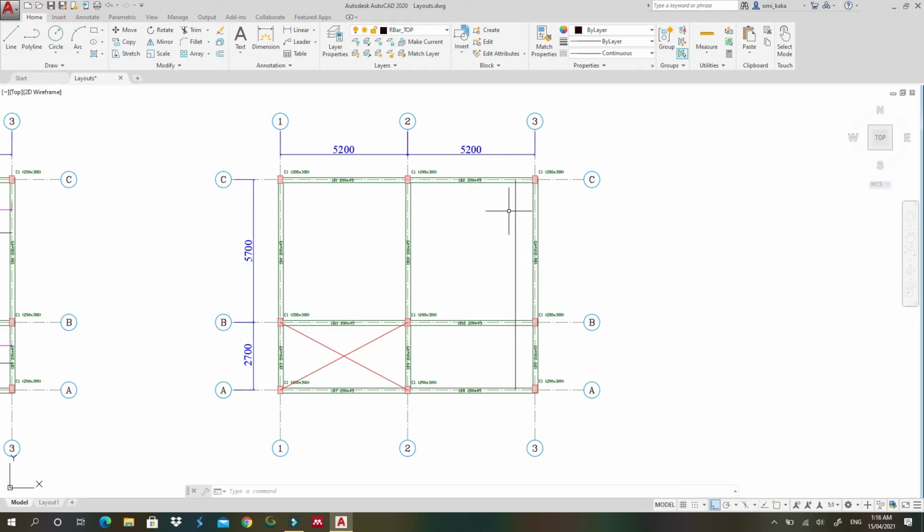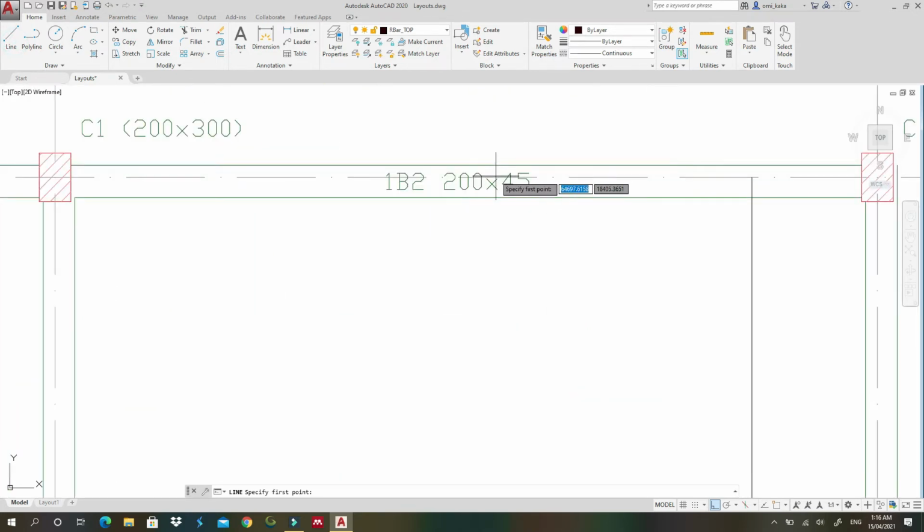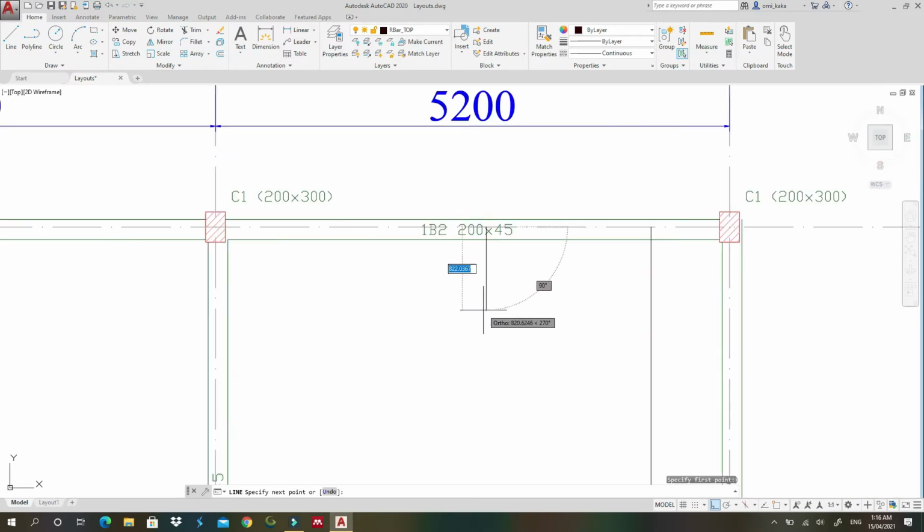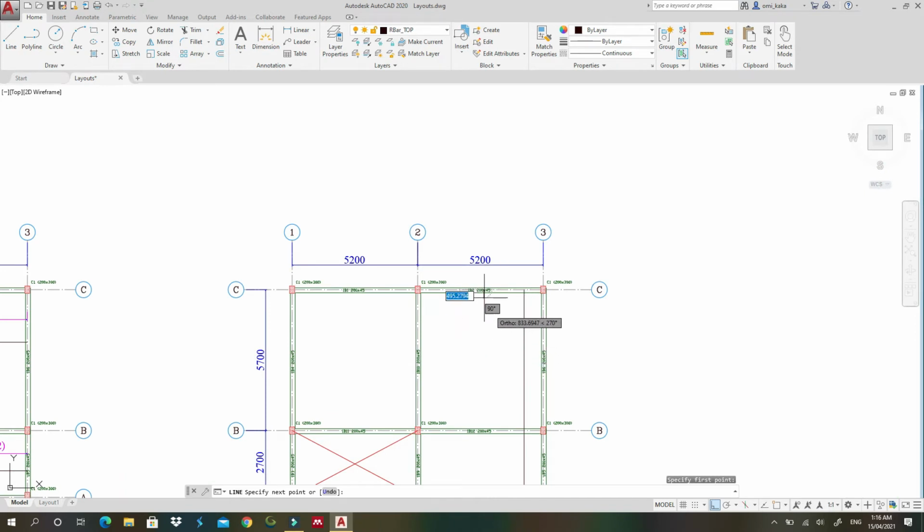So he'll arrange the first one, the second one, the third one, until he gets to 1/3 of this panel, and then after that you should show another one, which should be the height. The length of this bar that I'm drawing now should be 1/3 of this distance. So 1/3 of 5700, I'll take 5700 divided by 3, I'll get 1900. So I'll write here 1900.